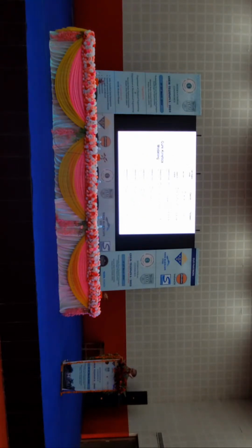Next one, please. These are different cure kinetics models. You have the data for d alpha by dt, the data for alpha, and the data for temperature. You fit all the kinetics models, because you cannot expect that every model will fit all resins; it depends upon the nature of the resin. So you have to fit the available models in the market and see which is fitting qualitatively and quantitatively.